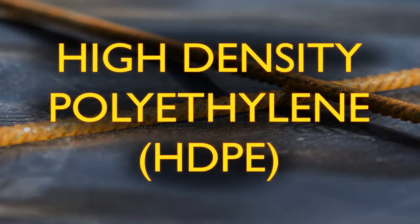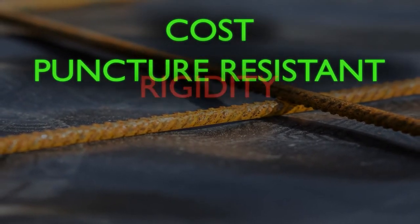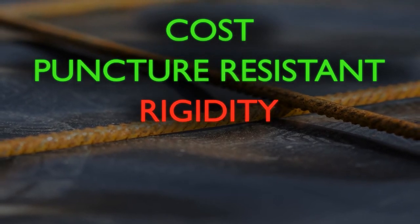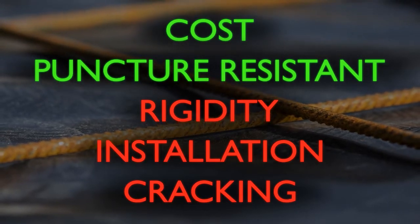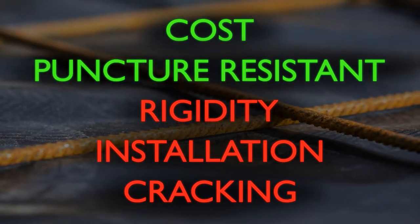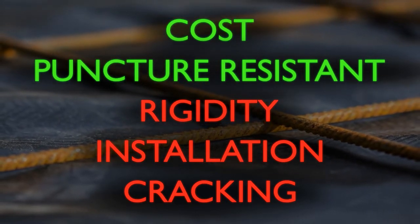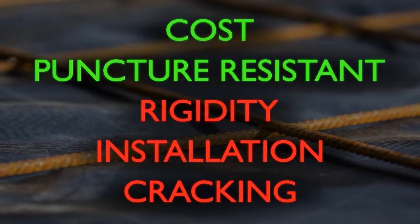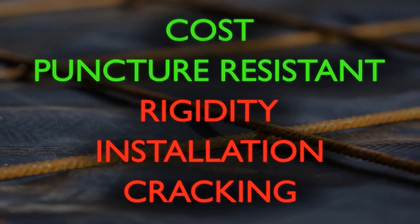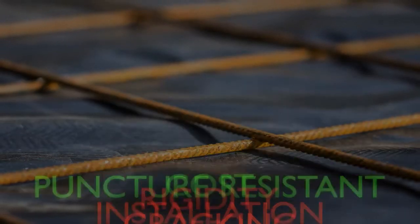High density polyethylene, HDPEs. HDPE is cheaper and offers good resistance to puncturing, but in comparison to PP is rigid and is therefore both difficult to install on complex details and prone to stress cracking. Any bending of the membrane to angles over 60 degrees is typically not recommended due to its detrimental effect on performance. Because of this mechanical weakness, HDPE is better suited to large uninterrupted floor areas, which is a good fit with roll sizes that they are typically supplied in. Like PP, HDPE membranes should not be tape jointed and require specialist welding contractors and verification.